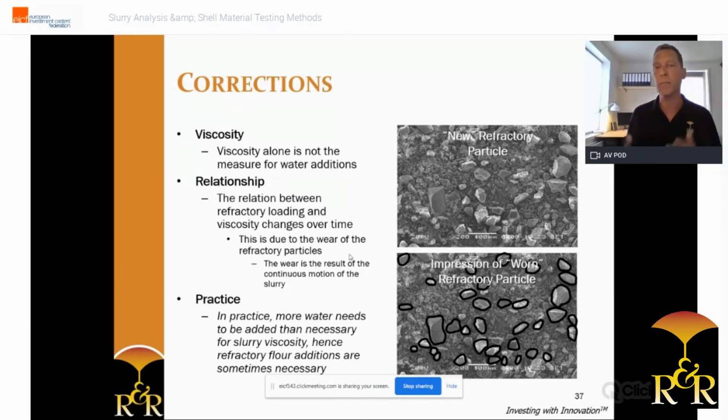So in practice, I recommend foundries to prepare a couple of times per week a small top-up recipe where binder ingredients are replaced by deionized water. It will help to reduce the impact of this phenomenon, and it keeps the binder solids within specification, which is so important for consistent performance. So it's better to make several small corrections per week than one big correction once in a while, to prevent fluctuations of the slurry characteristics.